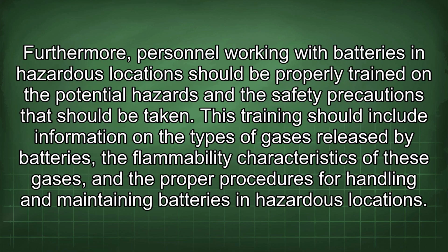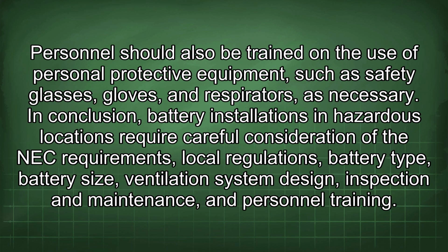Furthermore, personnel working with batteries in hazardous locations should be properly trained on the potential hazards and the safety precautions that should be taken. This training should include information on the types of gases released by batteries, the flammability characteristics of these gases, and the proper procedures for handling and maintaining batteries in hazardous locations. Personnel should also be trained on the use of personal protective equipment such as safety glasses, gloves, and respirators as